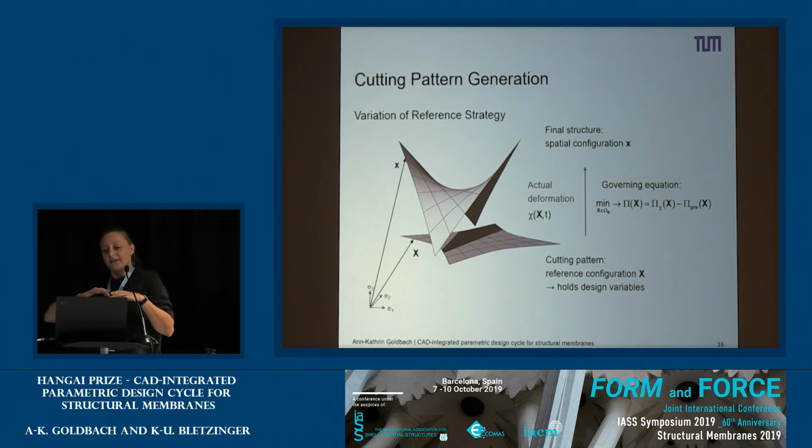So the projected surface is then allowed to move, so all the nodes in the plane can move around, and an optimization process is run to find the best solution, which we can build up and find the right geometry and pre-stressed state. And the optimization takes into account the potential energy which arises from this erection process.